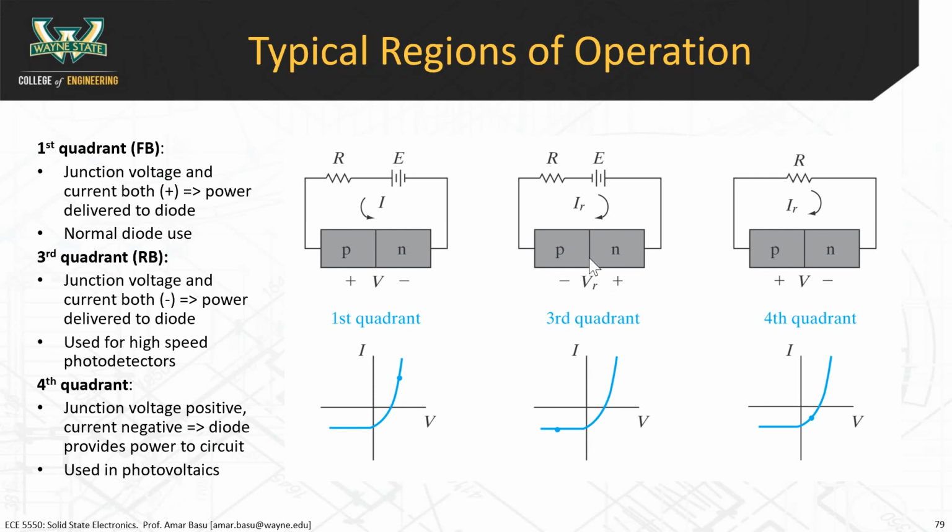Remember the two effects. Forward bias, you're decreasing the barrier height, you're decreasing the electric field in the junction, you're enhancing diffusion. That's forward bias. Reverse bias, you're reducing diffusion, and because there's more of a slope in the band diagram, that means you have more electric field in your depletion region.